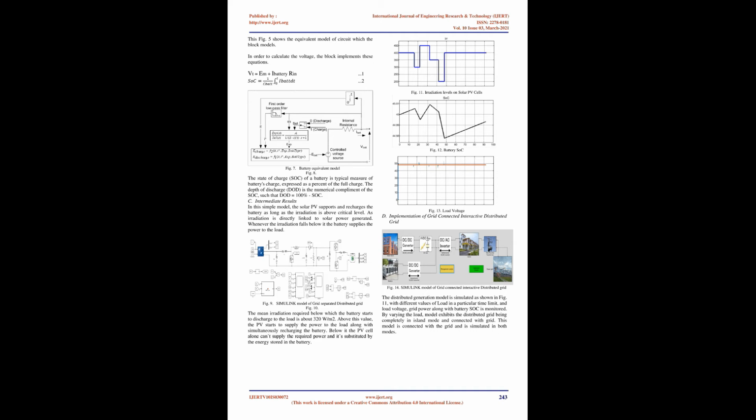Similarly, if a rise in voltage causes a decrease of power, this implies that the operating point of the photovoltaic is to the right of the maximum power point and hence more perturbation to the left is needed to reach the maximum power point. When the MPPT controller is implemented across the solar PV module and battery, it takes the solar photovoltaic voltage and battery voltage. It checks if the battery is completely charged or not. If the battery is completely charged, it then stops charging to prevent overcharging. If it is not, then it starts charging.